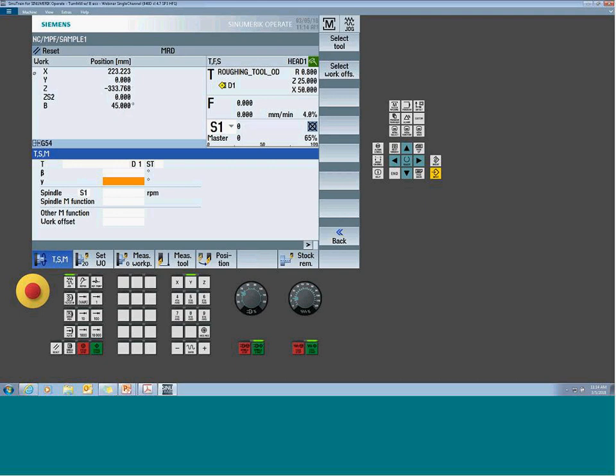But physical position and location changed. Now, the machine didn't move the linear axes. This is a dynamic offset, but that's not a 5-axis toolpath per se. But what it did do is calculate, based on that move, what you have to do to get back to that 0 point. So the system is automatically calculating for that. If I look at the actual motion of the machine, nothing really occurred.